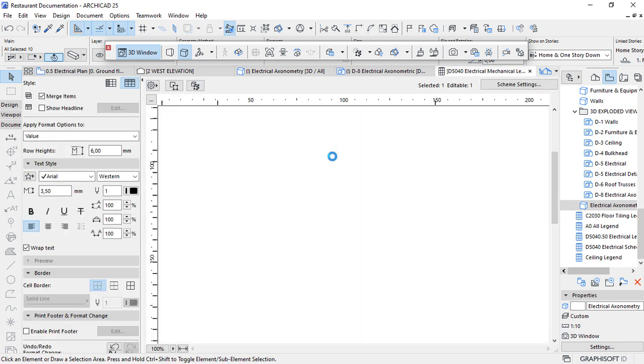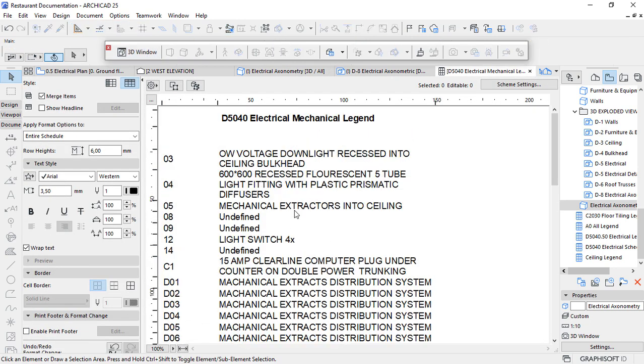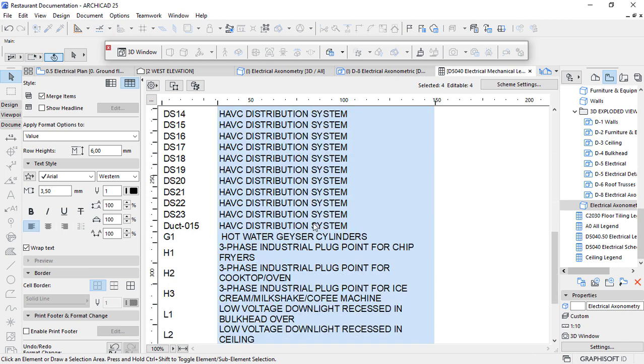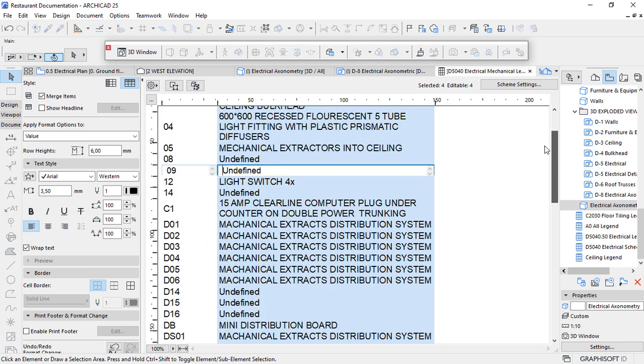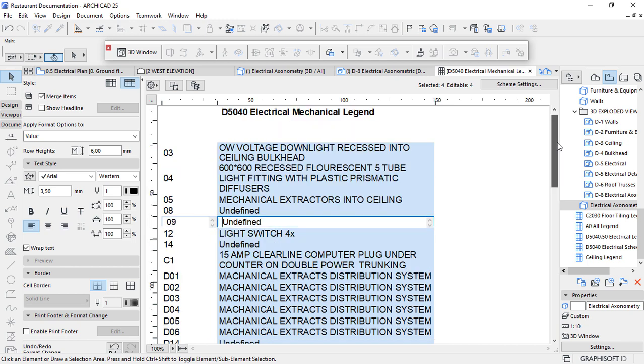And I'm pretty sure now the schedule table is looking great, so we can go ahead and fix all these remaining items. It's very, very important to do scheduling because it will give you an overview of the elements that are not specified, like in this case here. So it's always very critical to extract your information and assess to check if all the elements are being attended. So that's the reason for using BIM workflows.